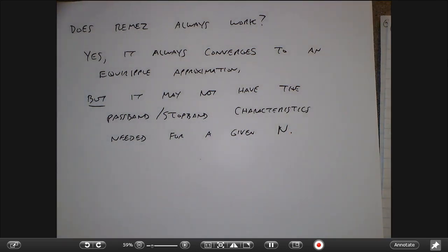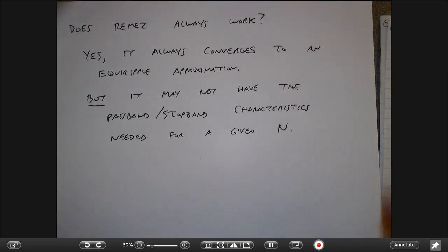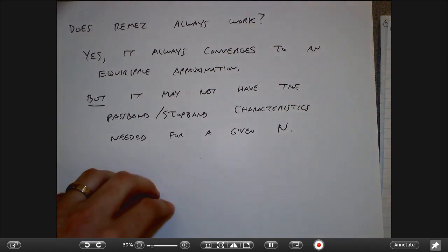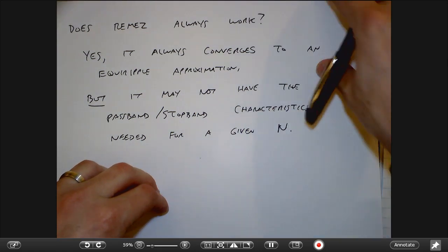Right? There are just some issues that you can't skate around. I can't make this ripple arbitrarily small if I only give you 3 filter taps. I can only do so well with a fixed amount of information. One nice thing is that there are a whole bunch of heuristics for if I give you 3 of these specifications, how do you find the 4th? So here's one simple heuristic.